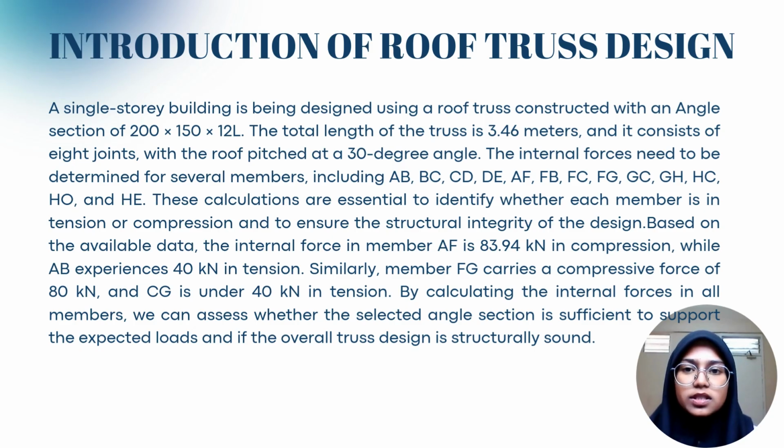So, here I'm going to present about the introduction of roof truss design. A single-story building is being designed using a roof truss constructed with an angle section of 200 times 150 times 12 L. The total length of the truss is 3.46 meters and it consists of 8 joints with the roof pitch at a 30-degree angle.